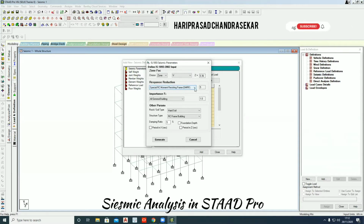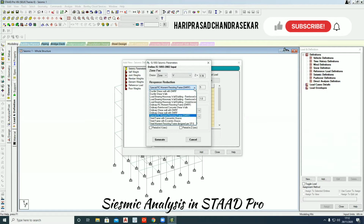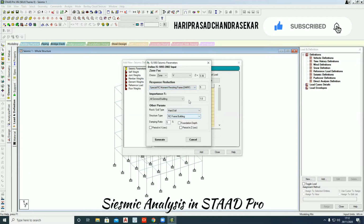And what I'm going to do means response reduction. Response reduction in the sense we have lots of options: ductile shear wall, load bearing, ordinary RCC. Normally they use special RC moment resisting frame, SMRF. Okay, it depends on your requirement. So I'm going to use the same special RC moment resisting frame. Okay, for that its value is 5. And even if you want to change, you can change it.